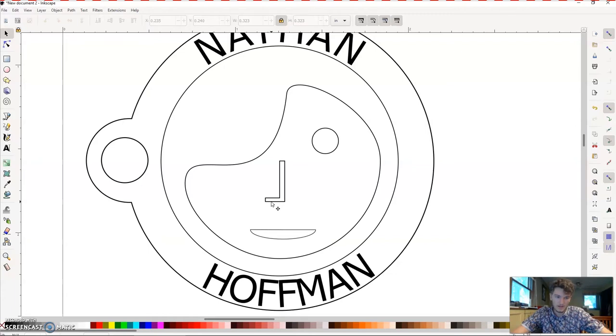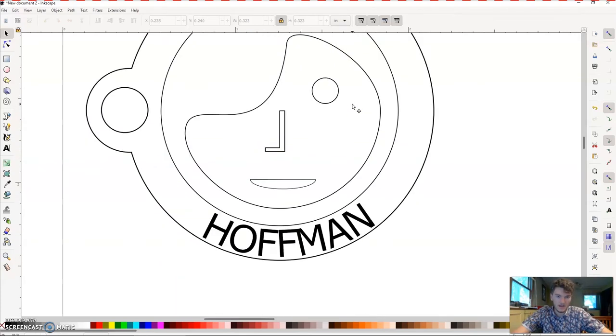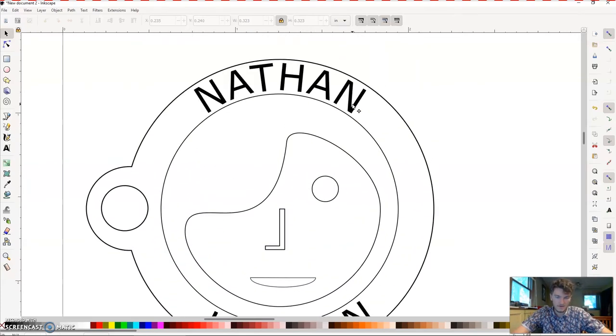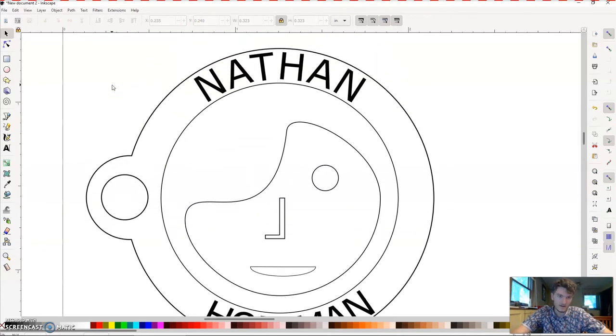But even if you can get it cut out, it's possible that 1 millimeter is just too thin for it to stand up for very long. So it's just generally good to not go any thinner than that. Now, that's mostly for cuts. For lines and engravings, you can go incredibly small. That takes a little experimenting, but you can get away with a lot there.